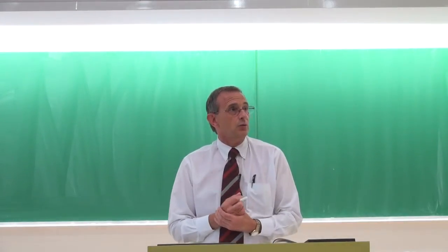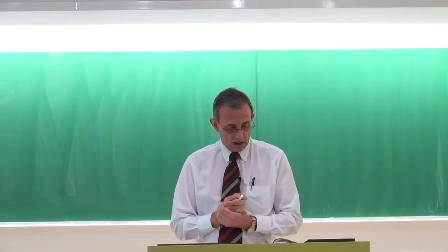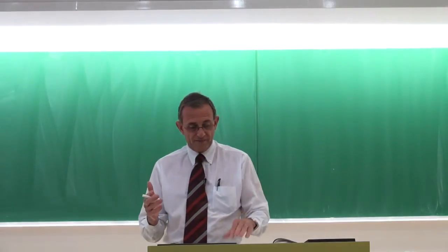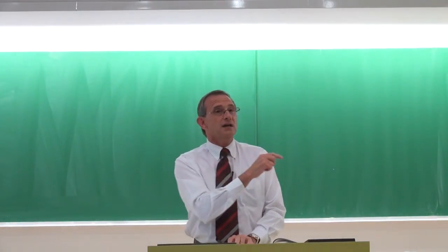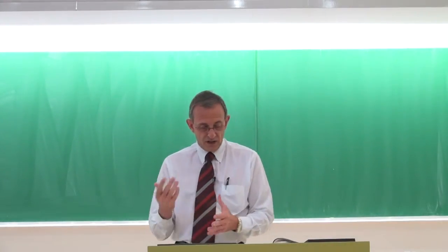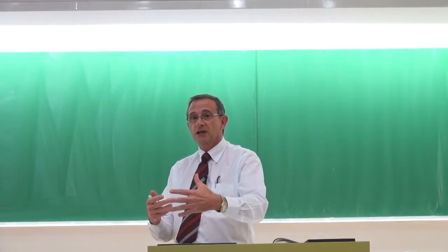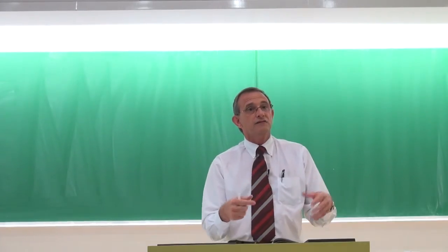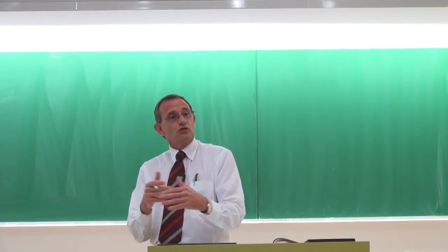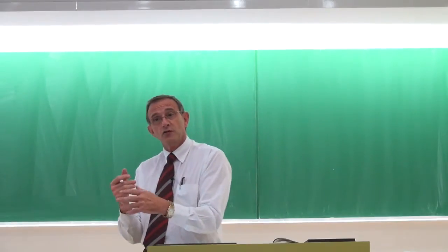Ladies and gentlemen, we are going to do now lecture 3 on internal forced convection. We have started in general with looking at the average velocity and the mean temperature of a fluid as it is being heated. We've done the entrance region in terms of how the flow develops hydrodynamically and thermally, and I've shown to you the complications in terms of the heat transfer coefficient and/or the Nusselt number, which is not constant. And I've explained to you the effect of the Prandtl number.